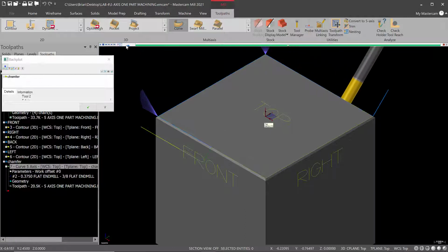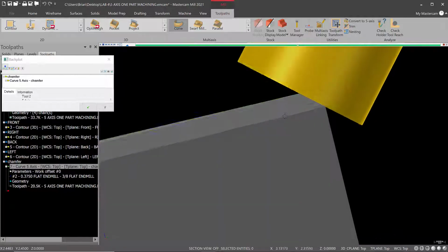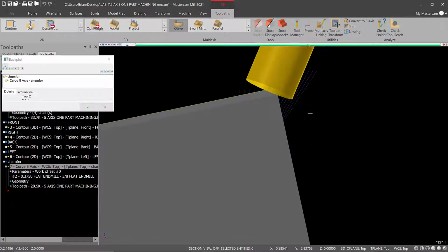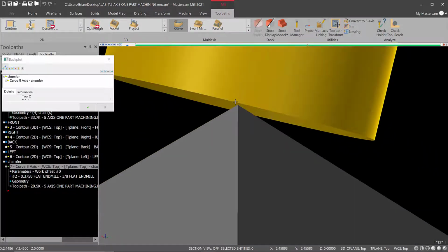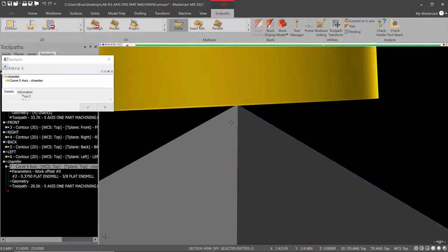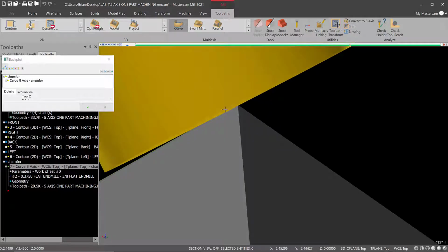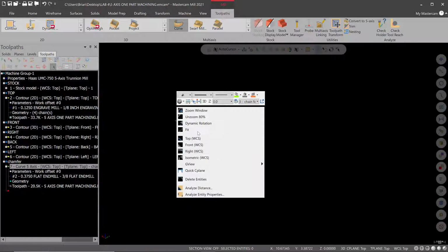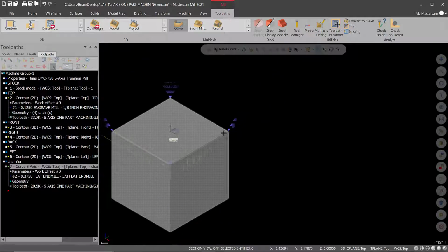All right, and we can slow it down if you want. Hit stop right there. And then hit S, and we can watch it tilt and make sure that it stays right with this crisp chamfer line right there like that. Just like that. So it should pivot right around. Okay, you see it flies right across because there's no real need to increment around those flats, in my opinion. I think it just makes the code longer than necessary and gets you the same results.